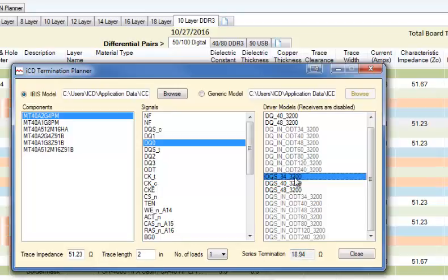But a DDR3 and DDR4 device should really work on a 40 ohm transmission line. So if we change this to 40 ohms, you'll see that a 34 ohm source impedance actually needs an 8 ohm series terminator, and this is because of the parasitics of the transmission line. It's not your simple lumped element network. If we program the device with a 40 ohm series terminator, then with a 40 ohm load transmission line, we still need a 2.81. Well, in that case, I wouldn't even worry about a series terminator because it's fairly closely matched.